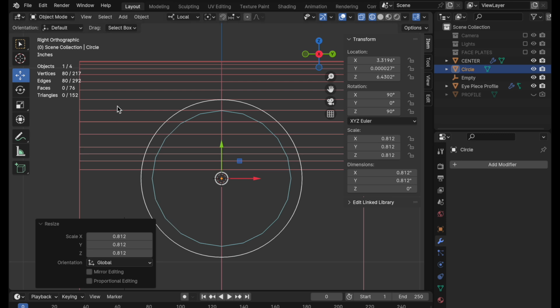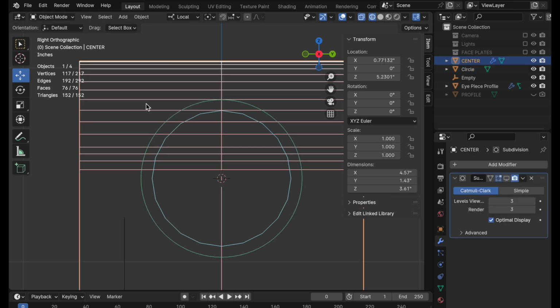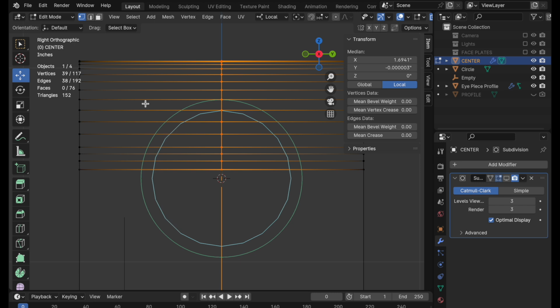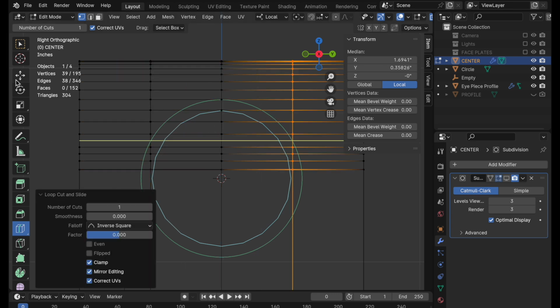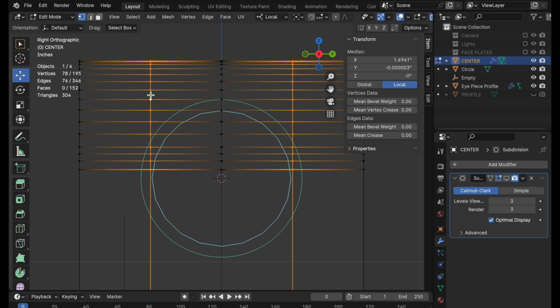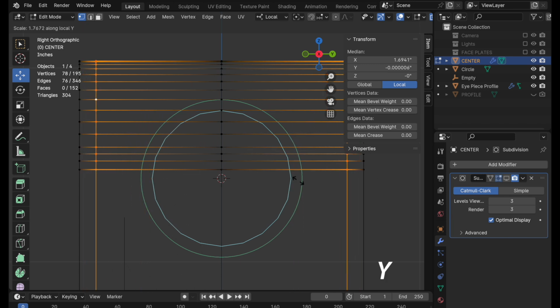Let's come back into edit mode, polygon edit mode for the main center piece of geometry, and let's add a loop on either side. In fact, let's do this. I'm just going to add it like that, and then I'm going to select both of those. Period key, make sure I'm in bounding box geometry. S and then Y, and I want to scale those out about like that.